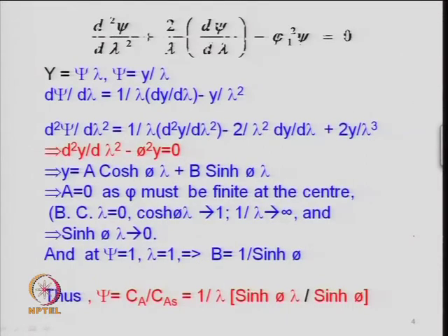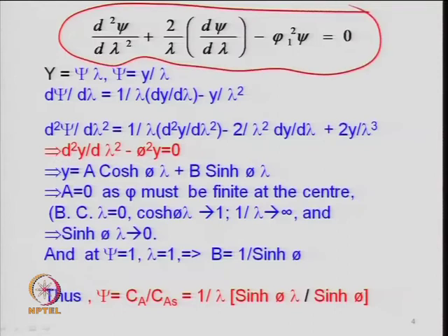In order to solve this differential equation, very quickly I will just go to this, that we try to convert this equation in a simplified form. That is the standard form for analytical solution, but one can use Bessel functions also for analytical solution, or one can go with the numerical technique as I discussed, finite difference methods. So, we defined a parameter which correlated psi and lambda together. So, y, another parameter, which is psi into lambda. So, psi can be defined by y by lambda from here.